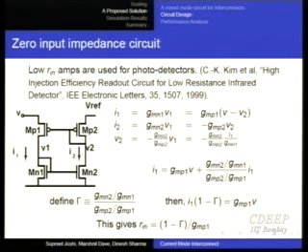So essentially what it means is that when the input impedance becomes 0, then to create a certain amount of current, I don't need a voltage change at all. Okay? You just nudge it a little, don't actually move. And in response, the current starts increasing. Right? Because of the positive feedback. So actual delta V is 0, but because input impedance is 0, the current can now change.